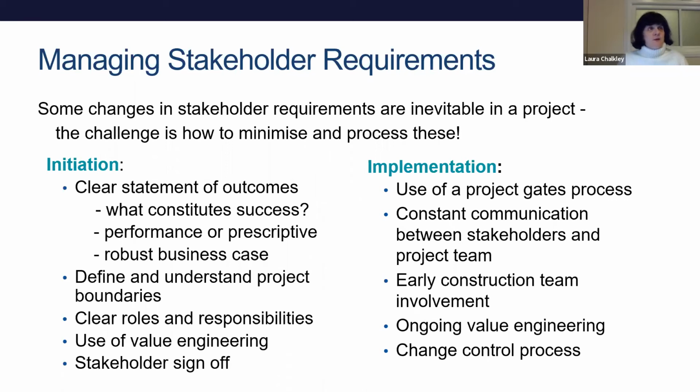The ultimate outcome might be a bridge, but is it going to be a concrete bridge? Is there a particular requirement that it needs to be a steel bridge? How many lanes? Is it better to define your specification as performance-based or prescriptive? Having worked with both methods, I like performance-based because that leaves the scope for the suppliers to express their innovation and bring their technical expertise into maximum play.